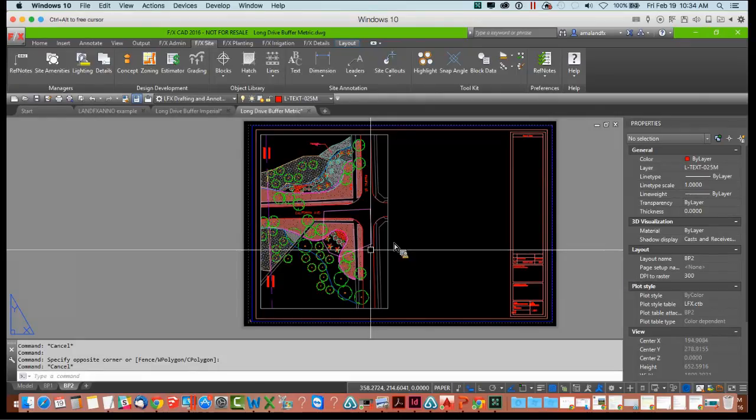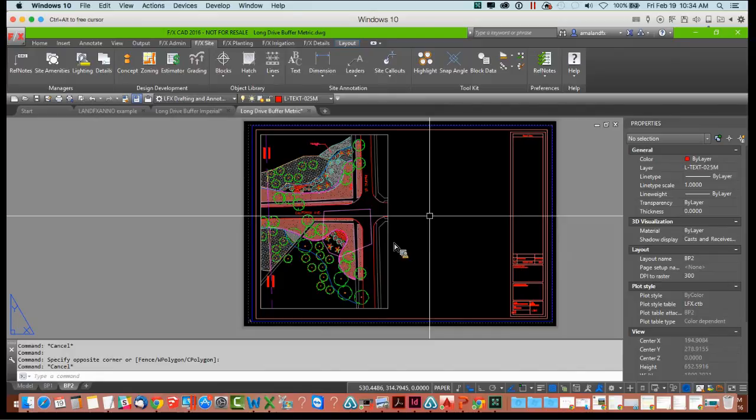Or if you're in Imperial, you might be going for more of a 1:10 instead of a 1:30, or a 1:20 instead of a 1:30, anything like that. You want two different scales, one layout space. Obviously, you need to stay in the same drawing for that. So what we're going to use is work areas. And if you watched the work area webinar 2 weeks ago, you got a preview of what I'm about to do, but we're going to show it off with some other cool things in it as well.